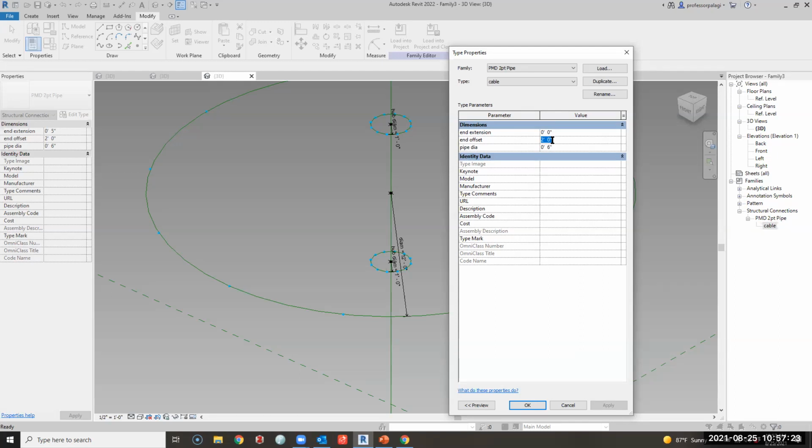Anything you're modeling, there's 2 reasons why it's nice to take that 3 minutes and make those 2 points that are offset in as a variable. One, the thing I'm about to do right now, you want to be able to see the point easy and grab it without having the object in the way of it. You have the pipe go to the end, it covers, and you can't grab that point again.